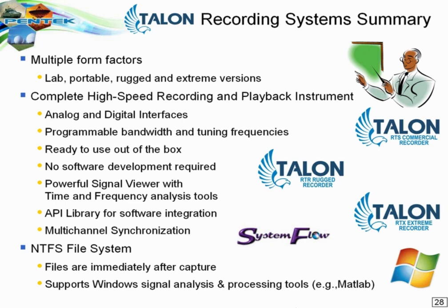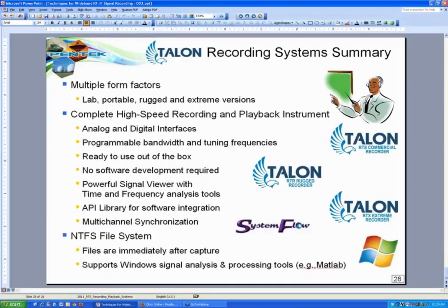So in any case, what we're doing is we're digitizing either baseband or IF signals. Usually, when we're dealing with an IF signal, the aliasing issue is taken care of because the IF output is typically band limited to the IF channel bandwidth. In the case of a baseband signal, however, you do need to ensure that you have a sufficient low-pass filter, let's say, before the A to D converter to avoid aliasing. Again, if you have the RF tuner block, this would be taken care of in the RF tuner.